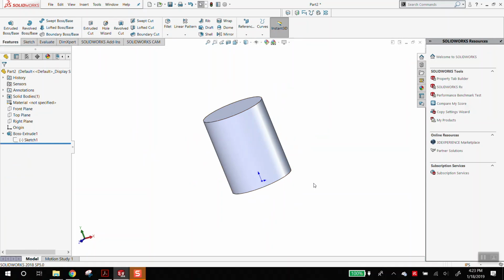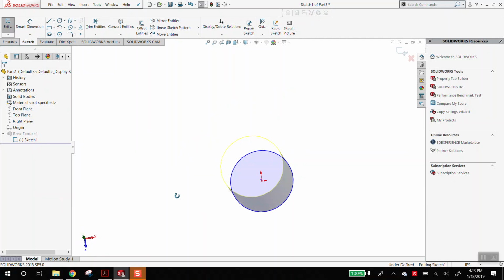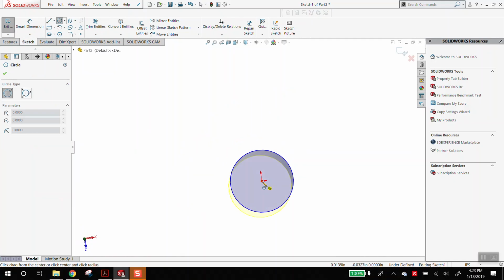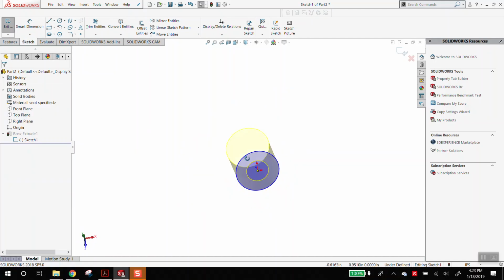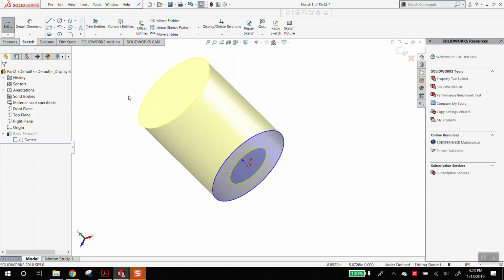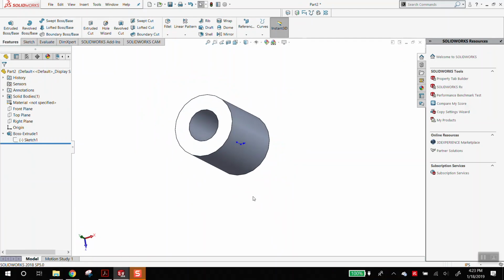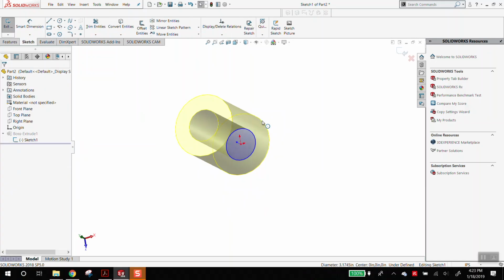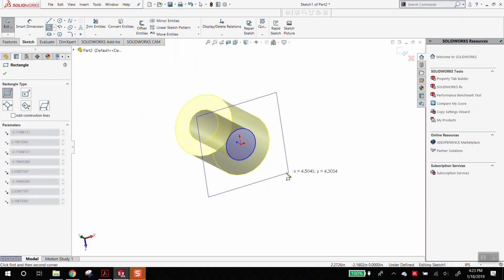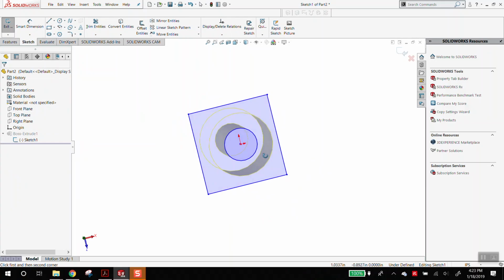So it's really robust. If I go back in here and edit it again, and now I use hotkeys, and we'll get into that. So I just hit O to get another circle. Let's see, this might confuse it, but my guess is it's going to give us a donut. So it's very robust and editable. Now where this becomes a problem, if I go back here, I hit R for rectangle. Again, the best workflow is using hotkeys.